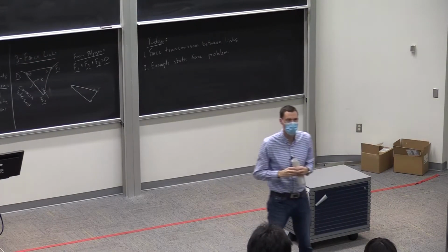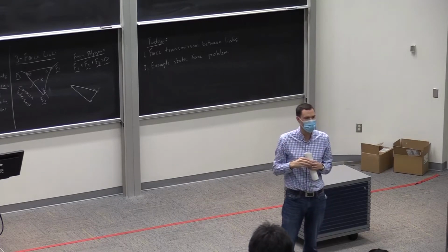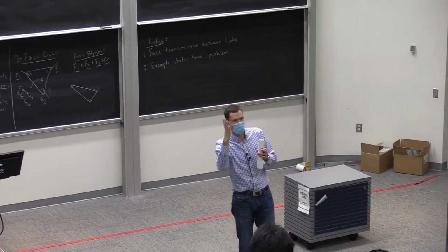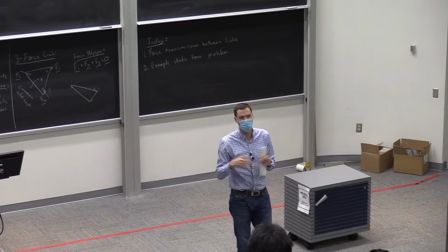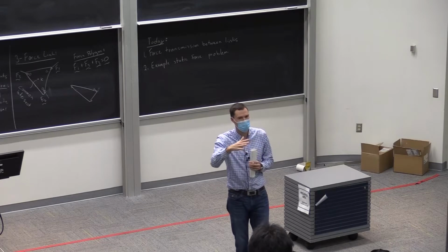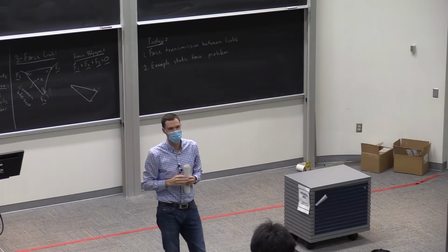So the way to find limit positions is basically do a little guess and check, sketch them out, and ask yourself, is that really at the limit? Or if I twist the input a little bit more right or left, or slide something, is that going to push it even further? So that's the first one to look at: is the input link perpendicular or parallel to the next link, or however the motion's transferred to the next link.